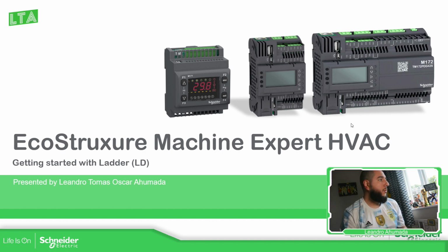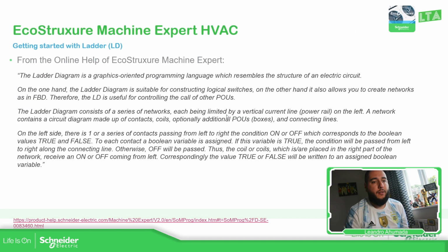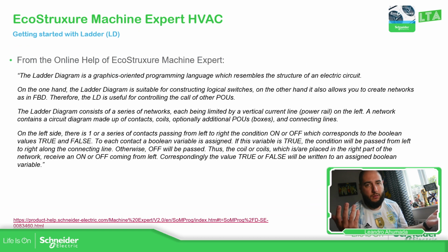So the idea of this ladder language that we have is basically made based on contacts and coils, and we also have the possibility to use function blocks. Basically, it's a graphical language. So based on the combination that we have with contacts, we can create our logic for the machine.